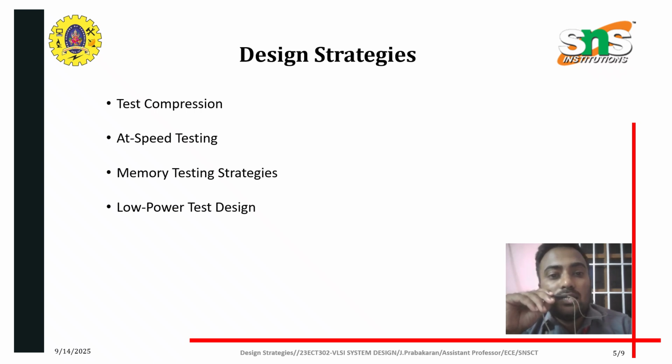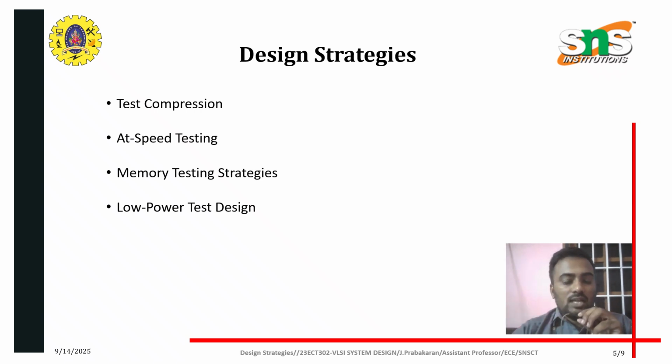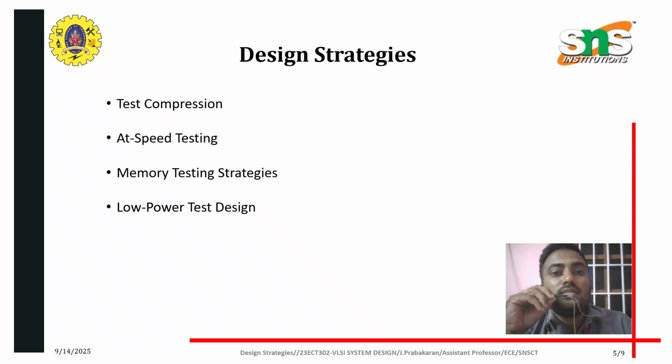And its methods are launch on shift, generally we call this LOS testing, and launch on capture, LOC, in scan testing, ensuring the chip meets performance requirements. And next thing is memory test strategies. Memories occupy most of the chip area in SOCs, requiring specialized test strategies.